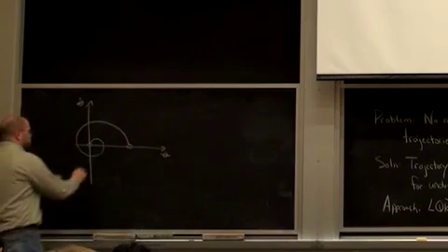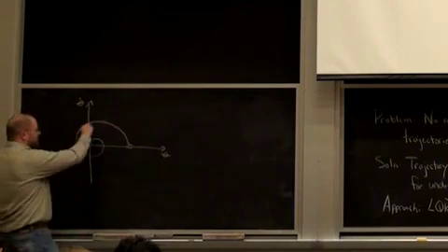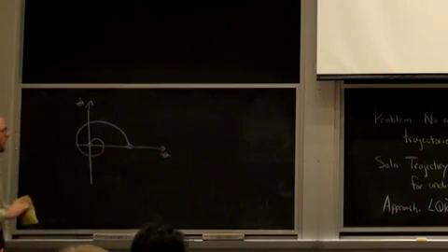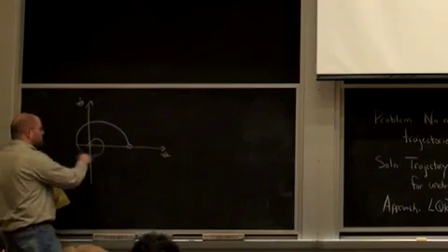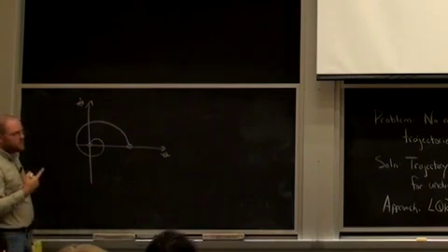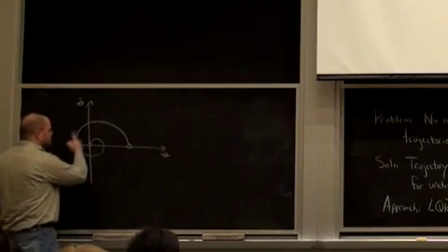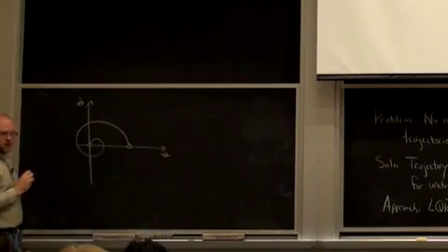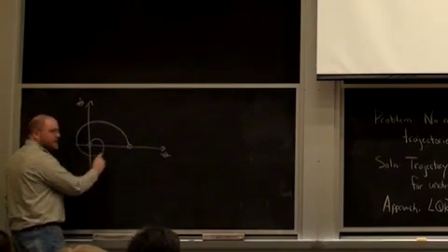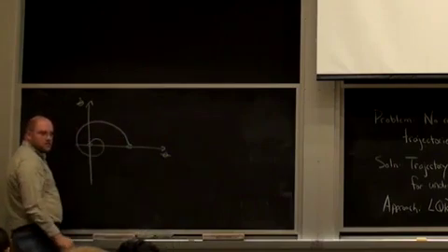I'm moving through state space here, and the dynamics vary with state in a nonlinear way, right? But if I have a feasible trajectory that goes through the relevant parts of state space, then this time-varying linearization takes my nonlinear system and, instead of being parameterized by state, makes it parameterized only by time along the trajectory.